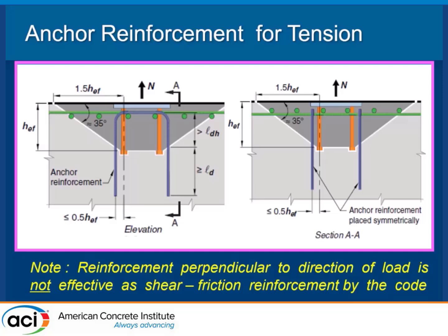In this case, you've kind of got a hook going here. I can make the case that when I do something like this, it's developed right here. But for the purposes of this conversation, I would have to develop here inside the concrete breakout and then develop it on the other side. And if I do something like that, I no longer have to worry about the concrete breakout. Okay? So that's kind of the whole key to all this stuff: what am I doing?